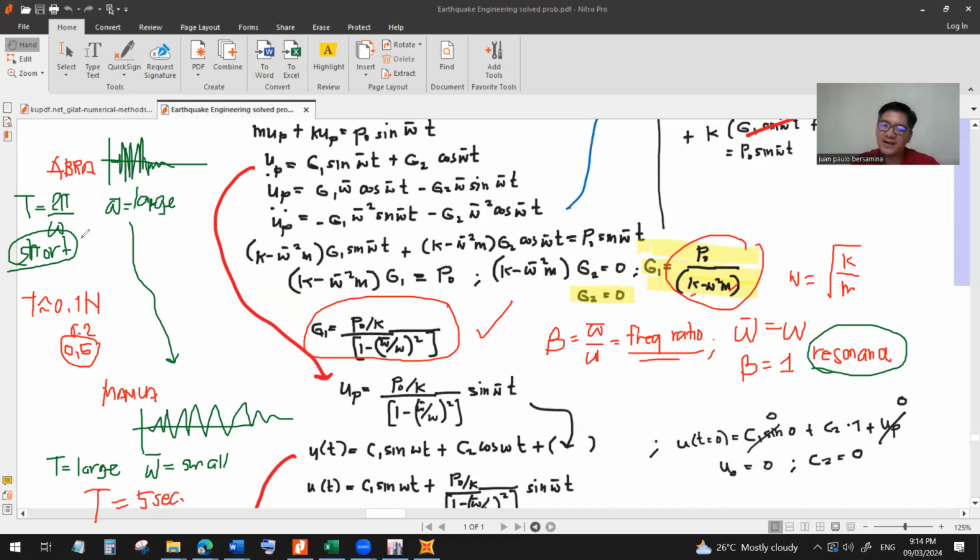Well, their construction methodology is a different matter. Most likely, that's also a main reason. But of course, since the period of the seismic wave is short, or omega bar is large, it will resonate with short period structures, which further justifies and causes the collapse.